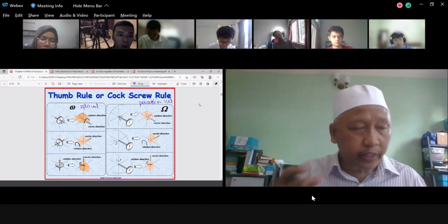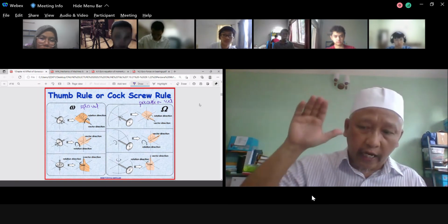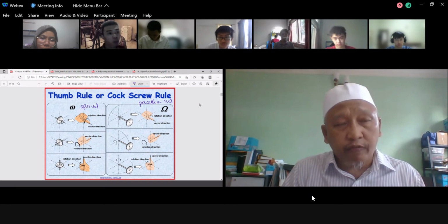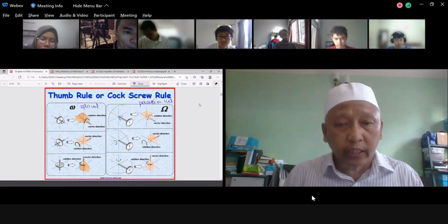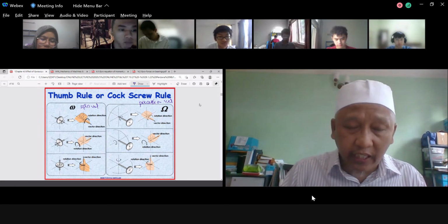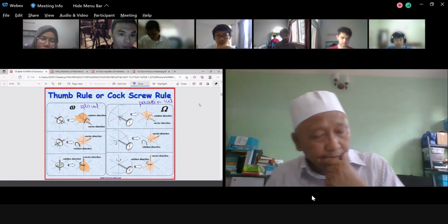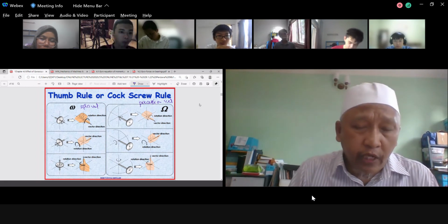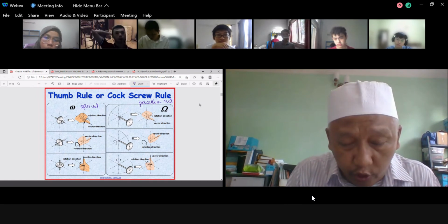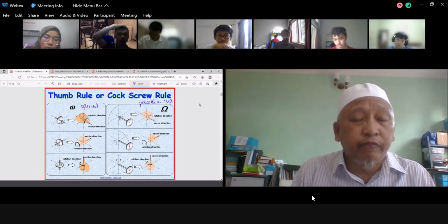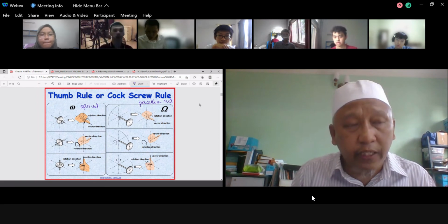The propeller now will be running at a certain speed, for example. Then the aircraft will turn to left, turn to right, diving and climbing, so on and so forth. So the motion of diving, climbing, turning to right and turning to left is the precession, while the propeller is rotating with the spin velocity. So the spin velocity is basically what makes the aeroplane fly. So bear that in mind. The other thing is, when we are talking about spinning velocity and precession velocity, in terms of magnitudes, numerically, the spin velocity is very huge, very big numbers, and the precession velocity will have a very small number.